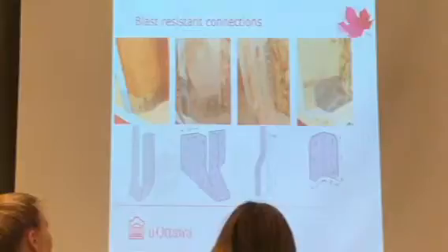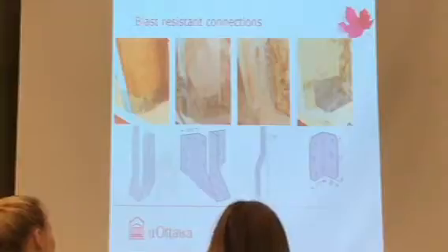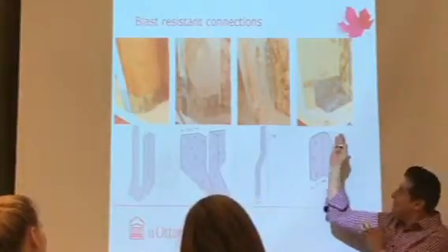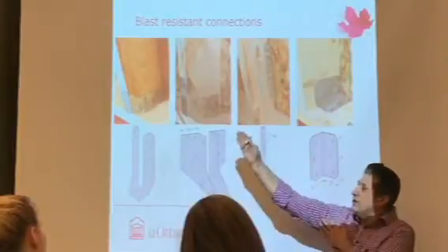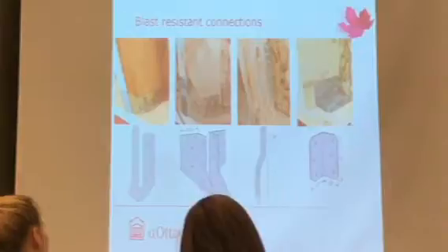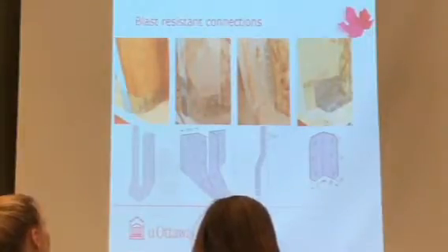So what you do is, let's say you attach it somewhere here, and then it twists, and then you attach it here. It just prevents that uplift from happening. I said, this is great, because when the stud starts bending and wants to go out, the strap is going to be in tension, and I'm going to attach it not just to the top plate, which all the other ones are done that way, I'm going to actually attach it to the blocking. So it's going to work very, very good. So I'll show you a couple of examples of the results.